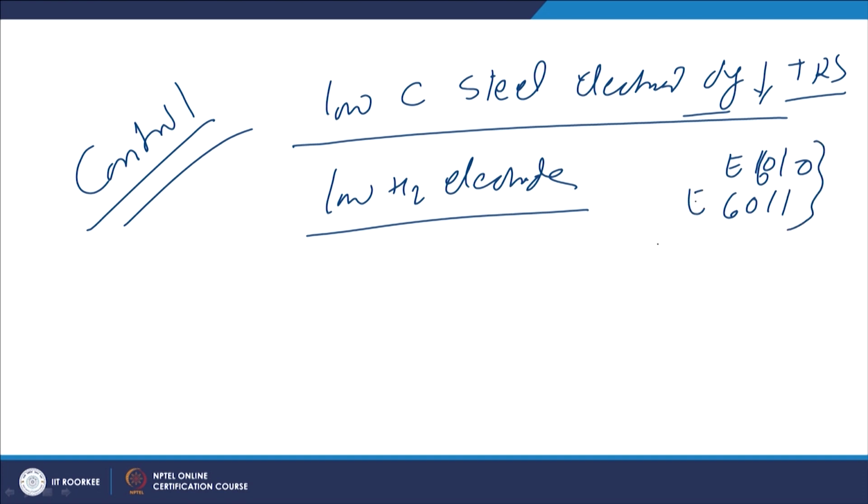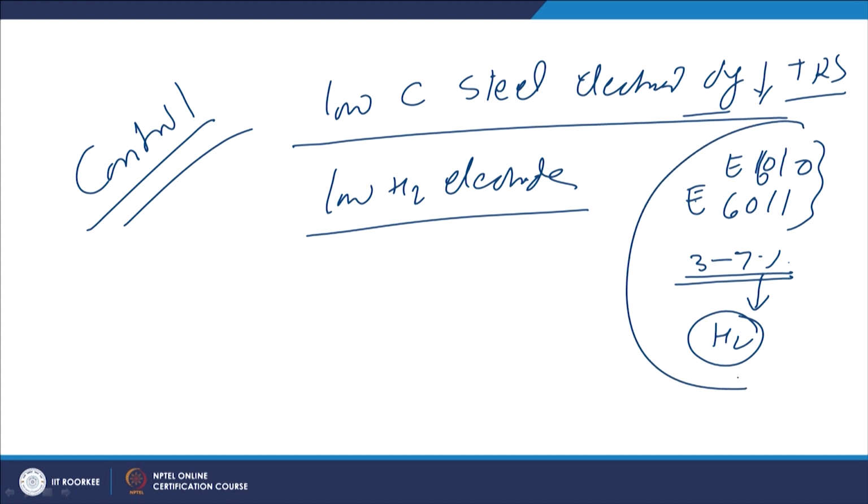These electrodes are cellulosic and have a moisture content of 3 to 7%, and the high moisture associated with such electrodes leads to a very high concentration of hydrogen in the weld metal, and thereby these promote hydrogen induced cracking. So, instead of using such electrodes, it is better to use low hydrogen electrodes, so that the cracking tendency of the weld metal can be reduced.